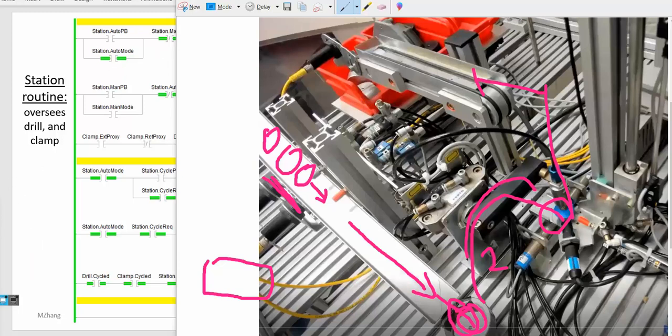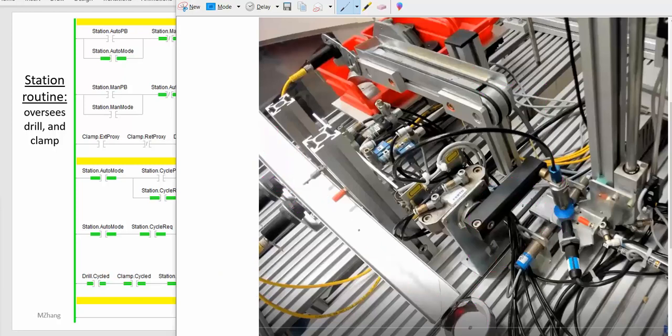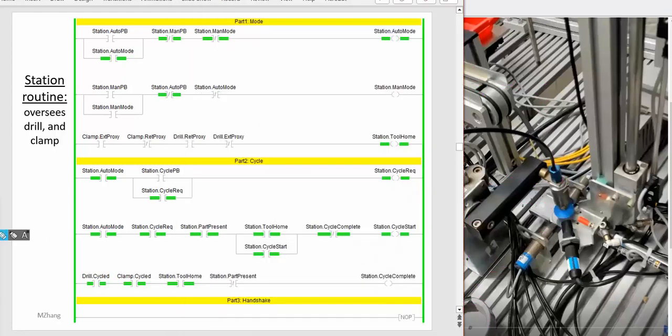So even though it's a different setup, if you think about it again, the solution is fairly simple, because with the automatic load and unload by the machine, we don't need to check part present off on here anymore. We just need to remove this condition, keep these 3 as the condition for the cycle complete. If you think about that, that makes sense, right?